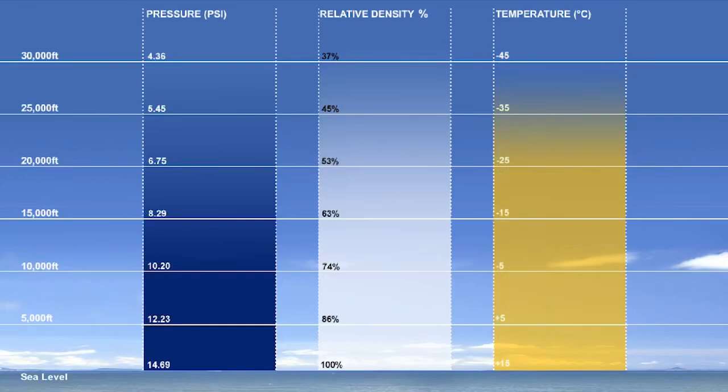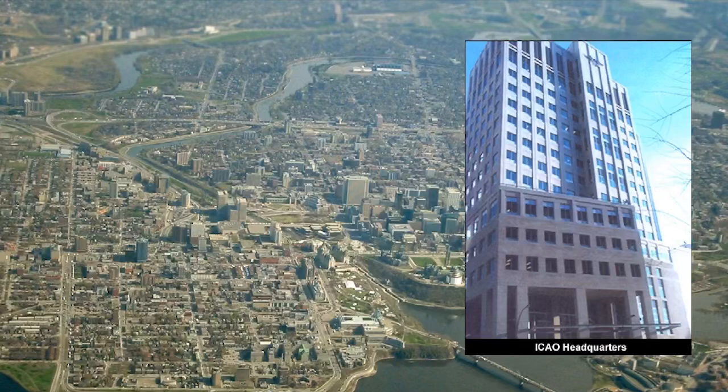Because the heat in the atmosphere is radiated from the surface of the Earth, the greater the altitude, the further away from the source of radiation, the lower will be the temperature. In order that an engine's power output can be checked in any part of the world, regardless of the ambient conditions at that place, manufacturers specify a set of standard maximum power RPM figures which are obtained on a standard day, according to sea level ISA conditions.